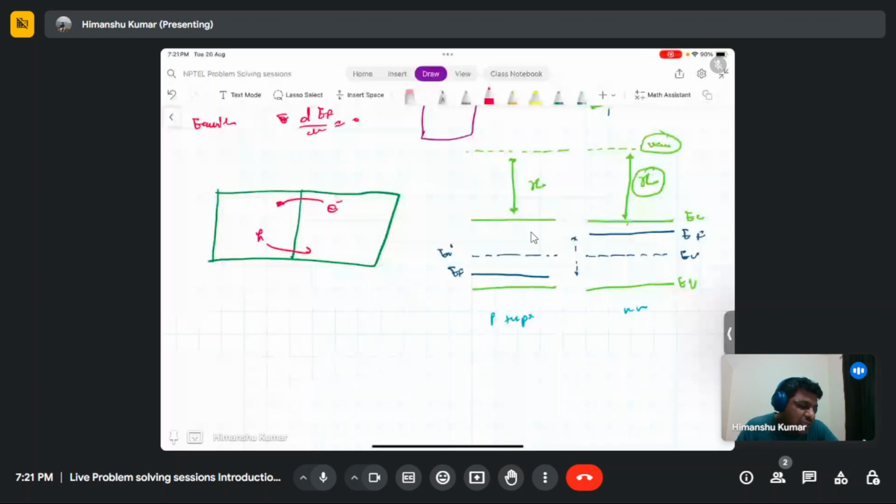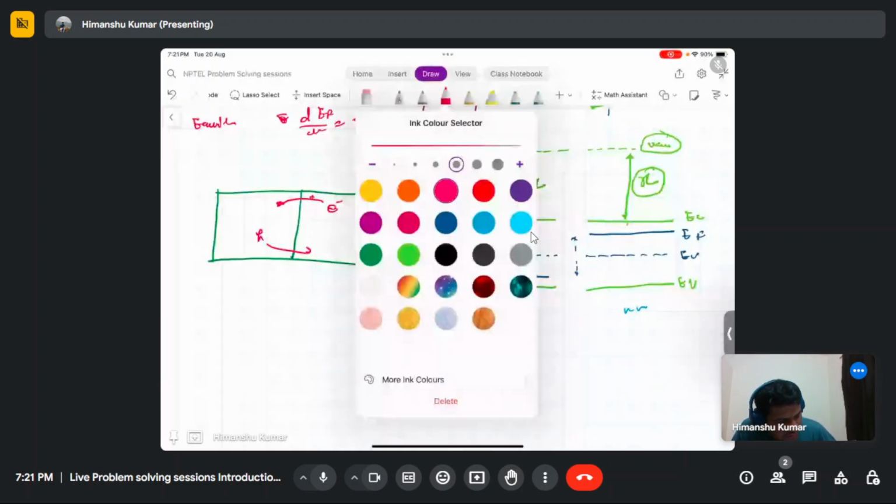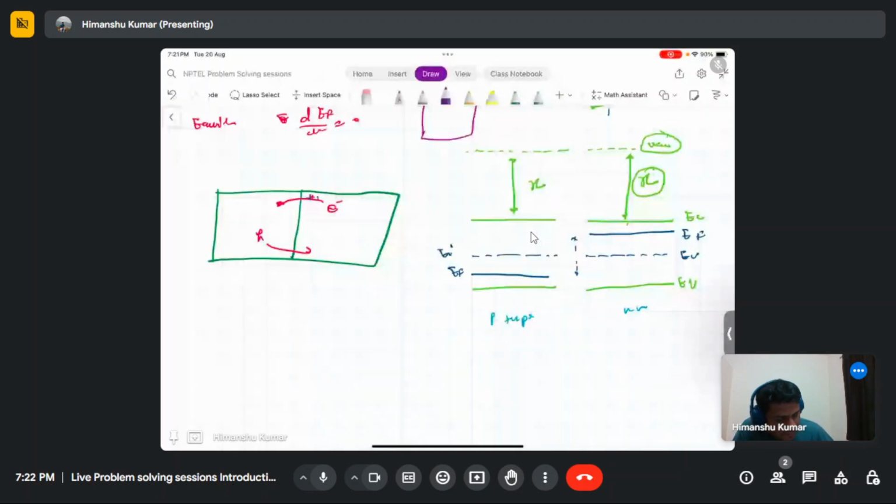After some movement there will be some positive charge here. Because the electrons have left, some ion cores remain, so there will be some positive charge which is immobile. That is because of the donor atoms which you have injected, and normally at room temperature or device operating temperature, whatever doping you have done can't move or diffuse, because to have those fixed ion movements you need a higher temperature.